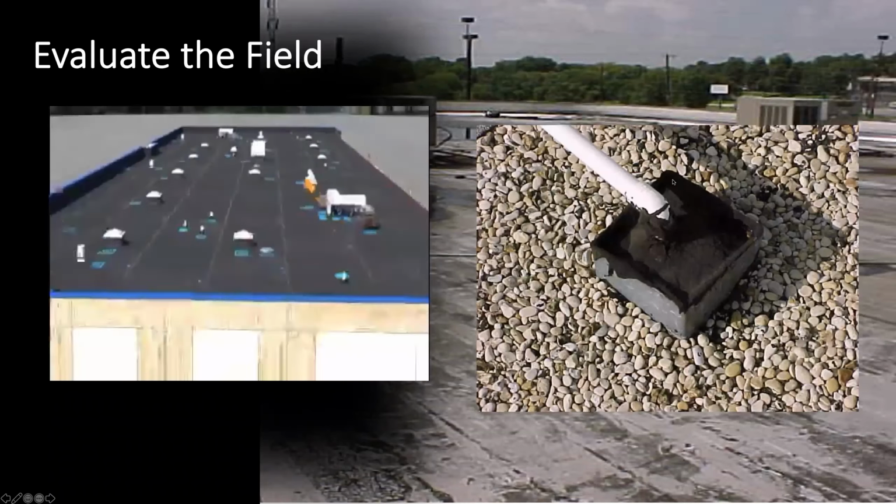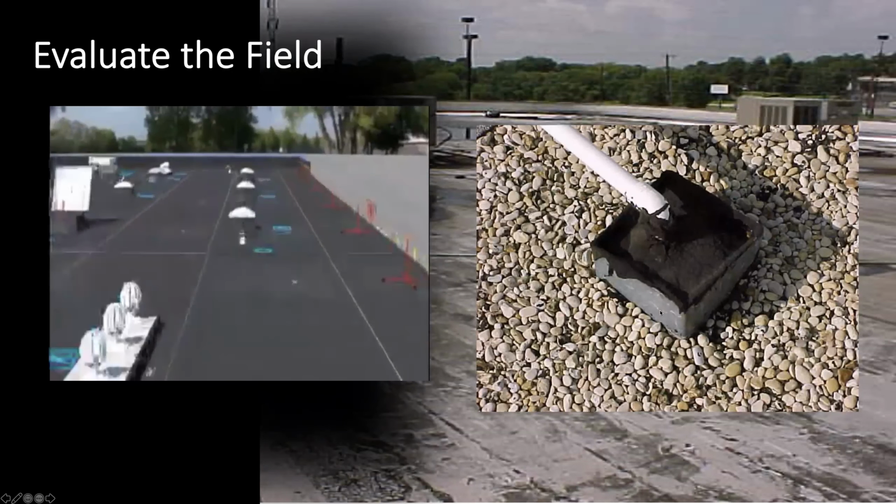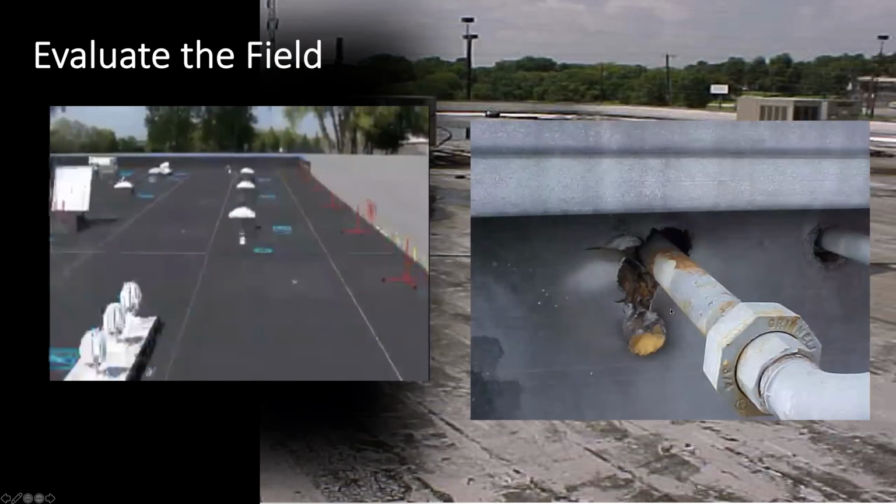And things that we see that are maintenance items out in the field, again, are these penetration type pockets where electric or gas pipes run through. The sealants that are used ultimately sink and break down, and this becomes a little water catch. The water has nowhere to go but down.